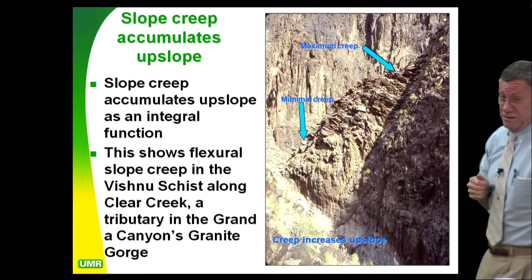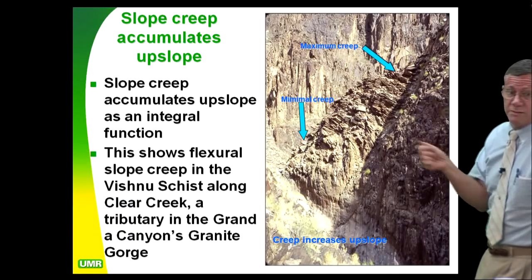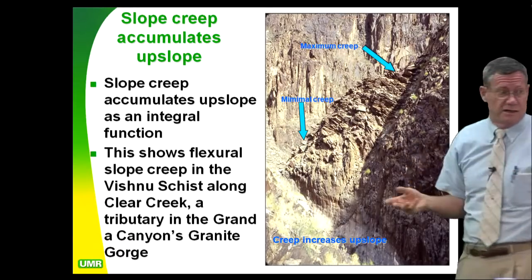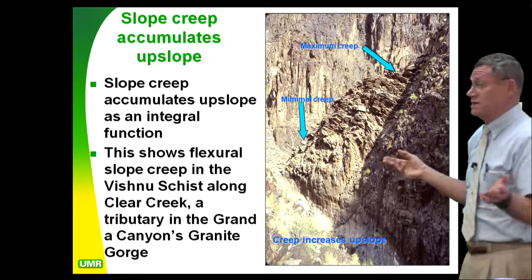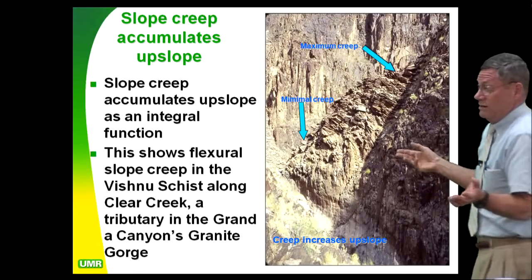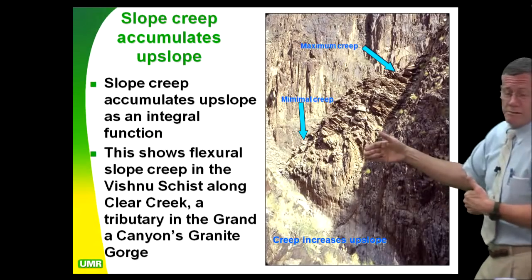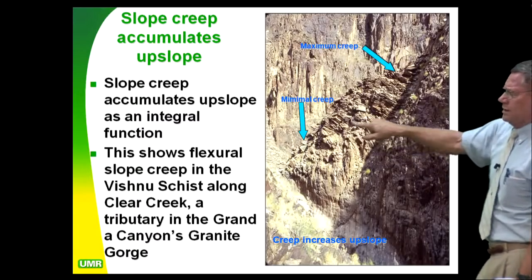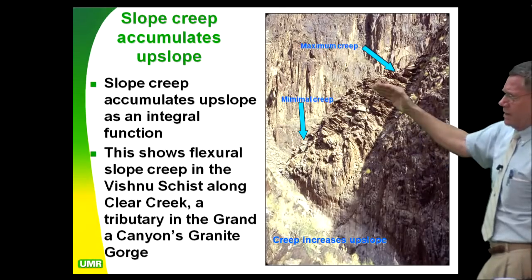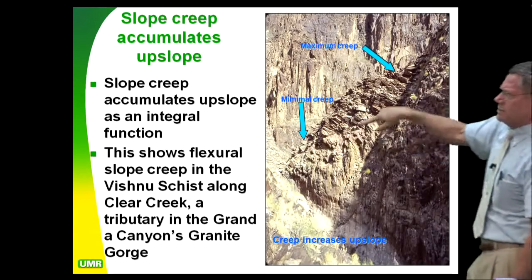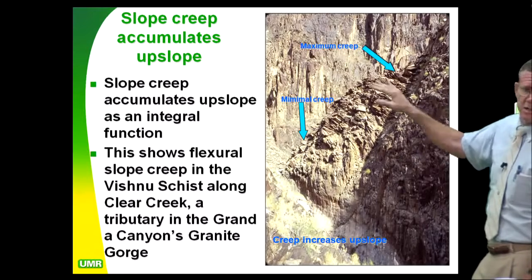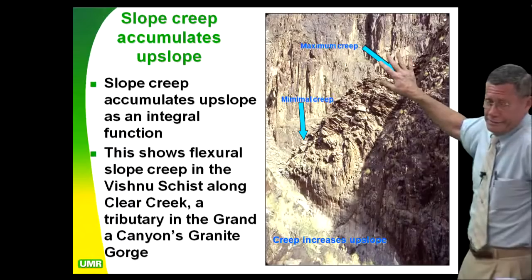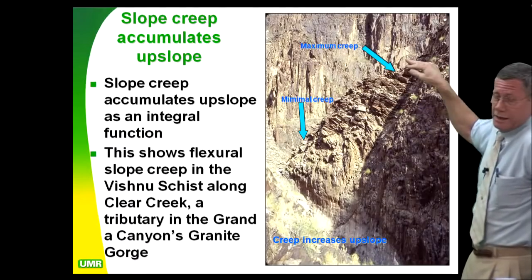And they're experts in this stuff now, because they go out and do a lot more instrumentation than we do, because they don't have a lot of money to spend $1 billion here and $1 billion there on slide repairs. They have so many slides, you can't repair all of them, so it's cheaper for them to move the highway than to repair some monstrous slide. So you're going to have different depths of movement and different amounts of movement, even though it's the same slide feature. And that's how slope creep works as well. So the place I have to be real careful is right up here, because I have the accumulation of all the strain going up the slope.